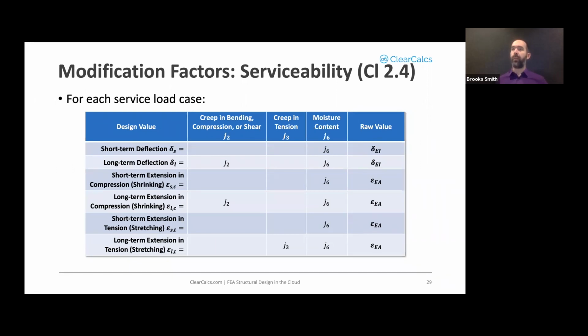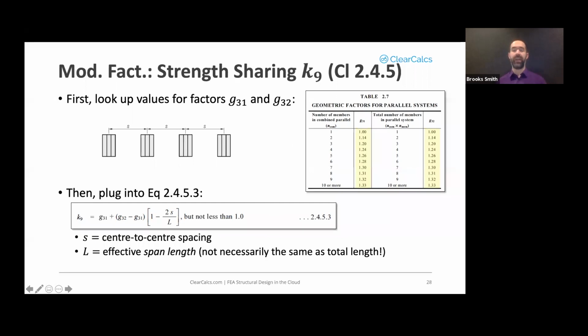So as far as the number of fixings that you need when laminating 2 different beams, unfortunately 1720.1 doesn't actually give guidance on this. It leaves it pretty much up to you as to how many fasteners, how many fixings you need to qualify as laminated.